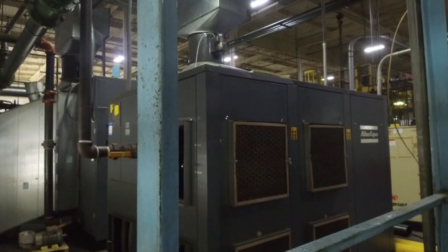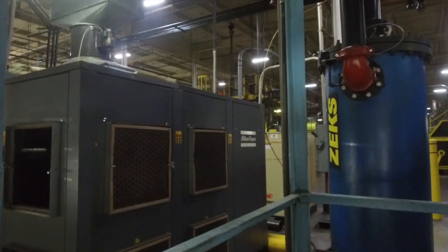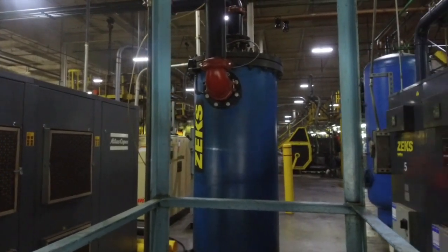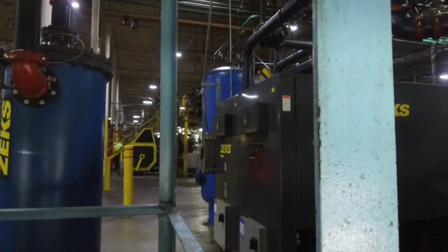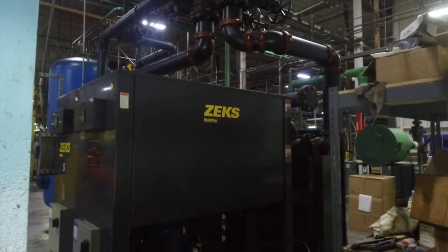Remember from episode 1 that when pressurized, the dew point of air rises significantly. So condensation is going to form when compressed air cools down. Now, a lot of this is taken out by air dryers, but receivers also collect condensation to protect end-use equipment. However, you have to make sure that your receivers don't overfill with water by emptying them regularly. Receiver tanks can collect up to 1,200 gallons of water per year. This means that a standard 55-gallon drum will need to be emptied about 20 times a year.